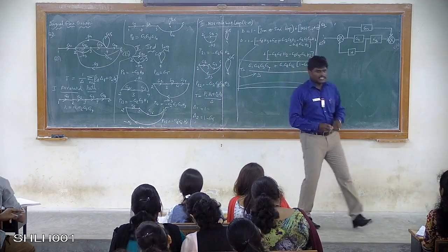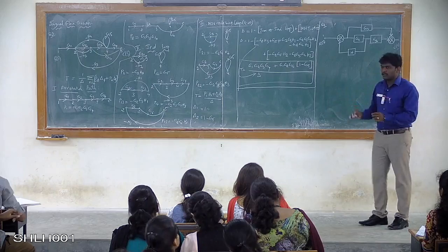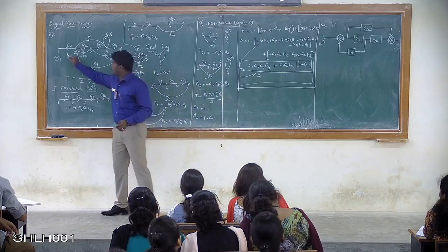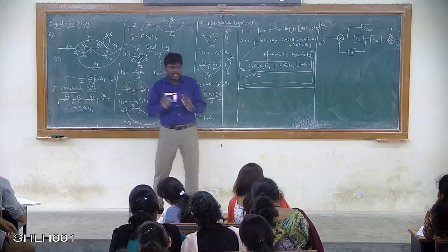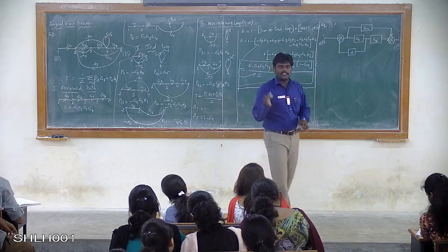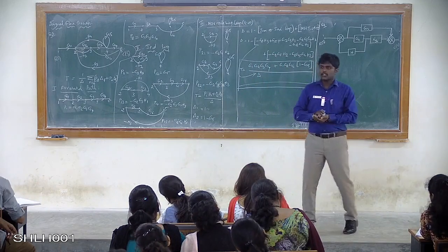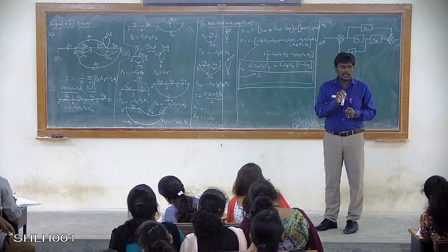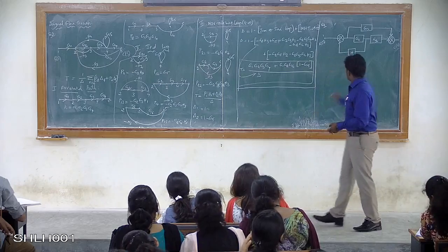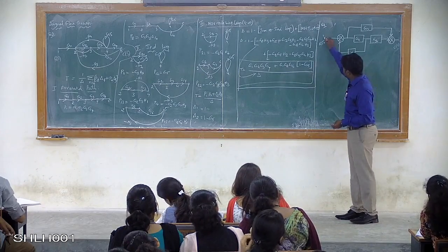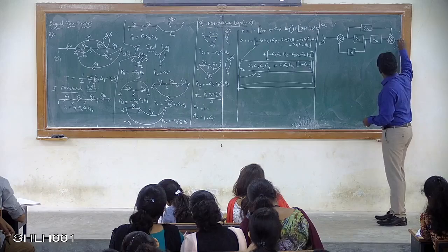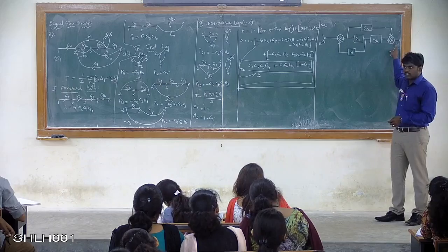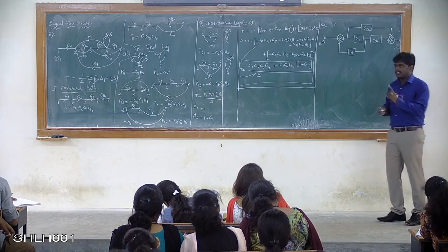So now the first step is that we will have to note down the nodes in the block diagram, right? So nodes means we have 1, 2, 3, 4, 5, right? Likewise, here we will have to identify which things can act as a node. A node means where a branching point may leave or come and join in that particular node. So first, the input as well as the output has to be taken as node numbers, right? So one and the other one has to be taken as a node number. That is the first step.